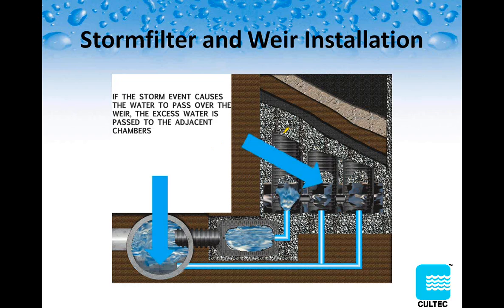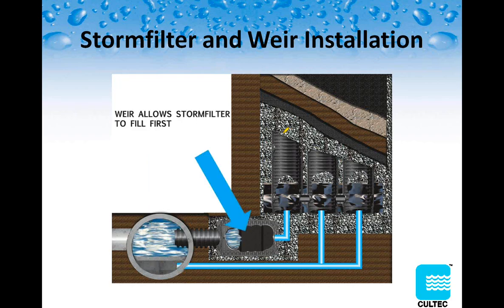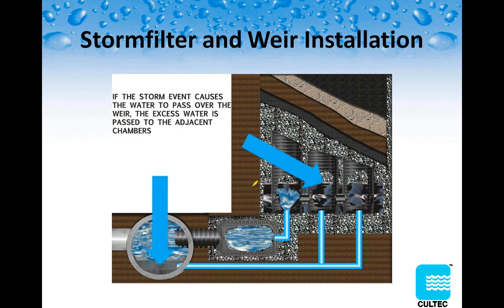Now when the storm system intensifies, that stormwater will overflow that weir, and at that time the sediment would have dropped out into that weir or been collected in that storm filter, and the cleaner stormwater will bypass that storm filter and enter into the system. And as you can see with the storm filter, before it opens up, there's a turret at the top that you could bring up to grade with a manhole so that it can be accessed and cleaned out just like a tank with a typical vac pump truck.